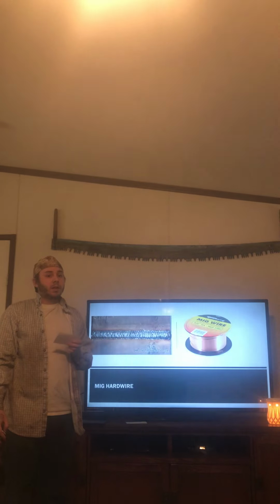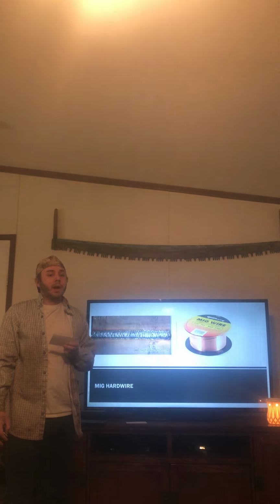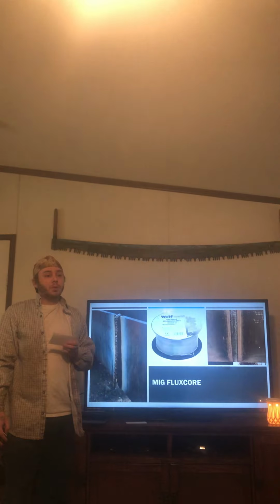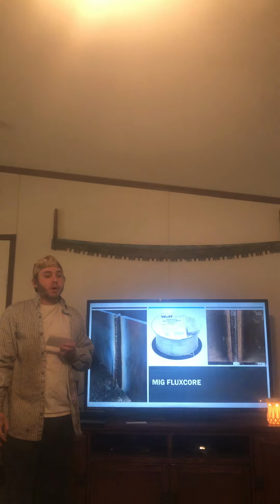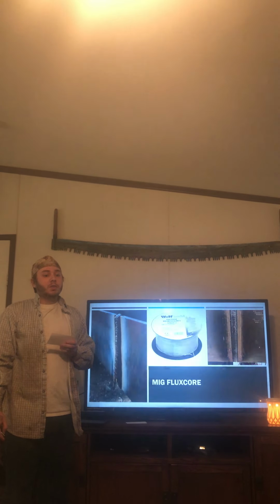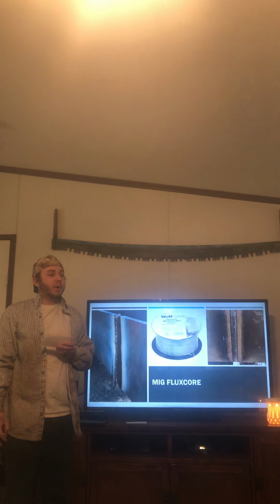You can weld in literally any position with this wire type: uphill, downhill, flat, horizontal, overhead, diagonal, etc. Another type of welding wire is flux core. It's a bit different. Flux core uses a flux-filled wire as well as shielding gas. About a 75-25% argon and CO2 mix is often used during this process. This dual shielding process achieves ultimate penetration with two shielding properties and is a choice of many structural welders worldwide.